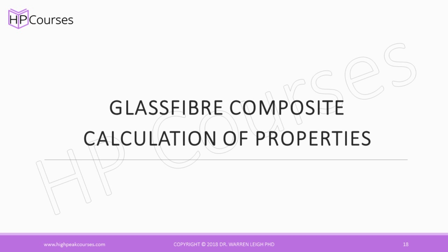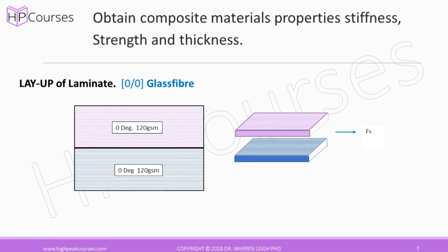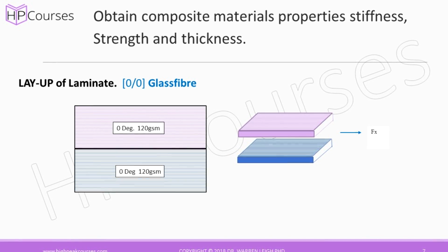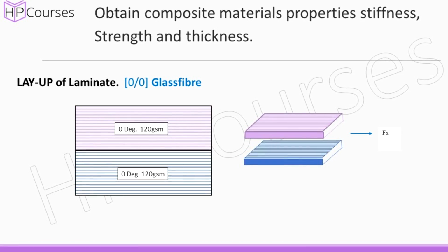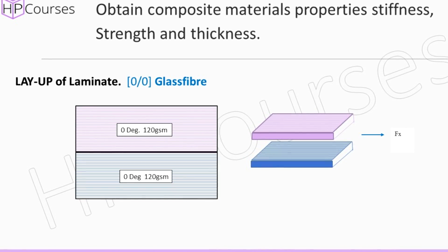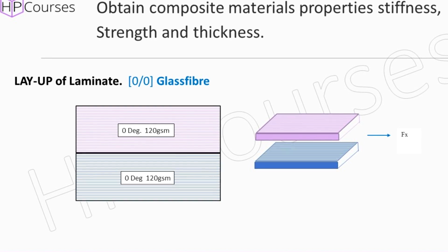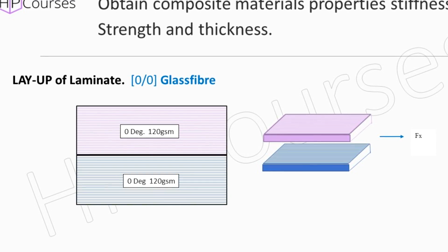We start designing the laminate architecture by first determining the Young modulus of our selected layered composite. A simple composite laminate in a resin, also known as a layup, consists of two layers of unidirectional glass fibre fabrics. This means that the fibres of each layer run in direction 1. Our material axis of fibre direction 1 aligns with the geometry reference axis of X. One layer of unidirectional glass fibre is placed on top of the other layer.